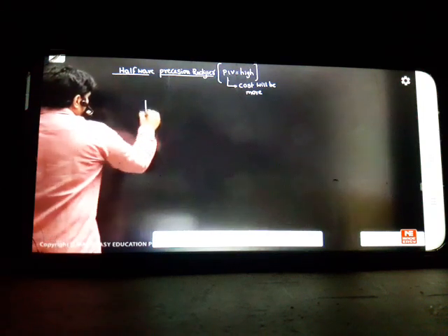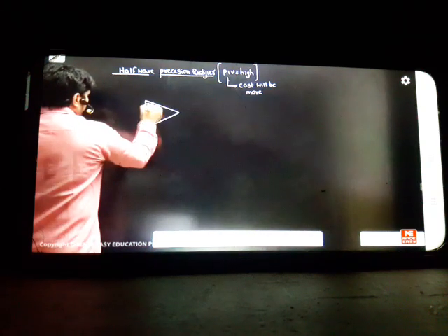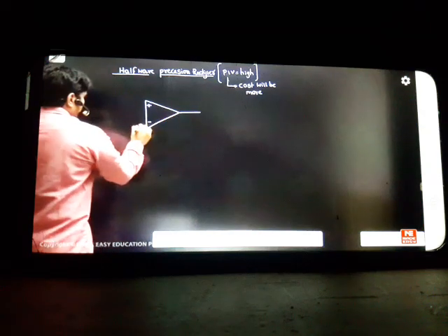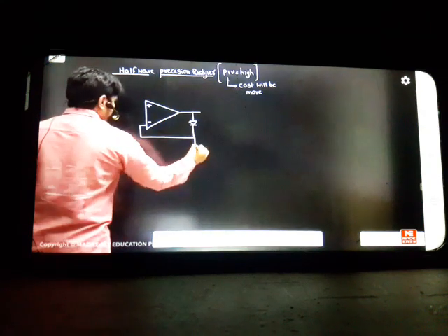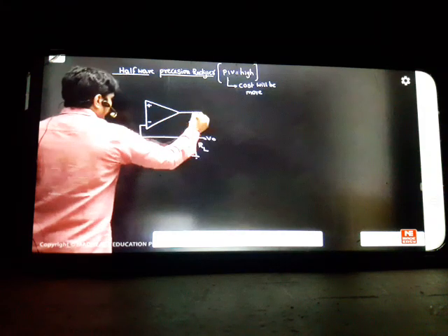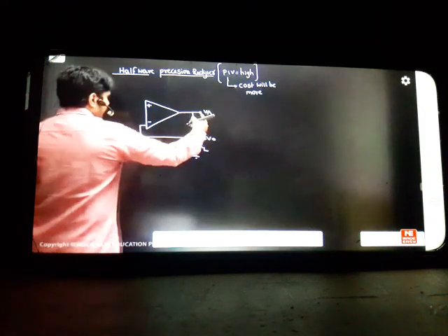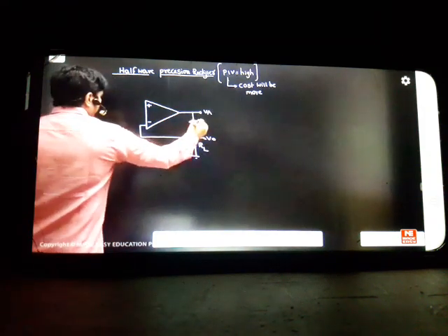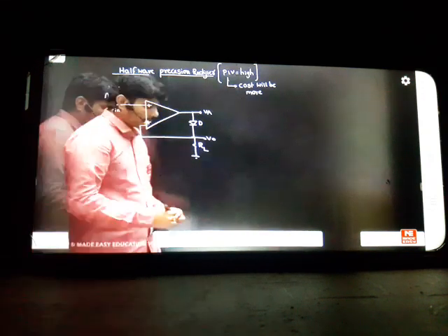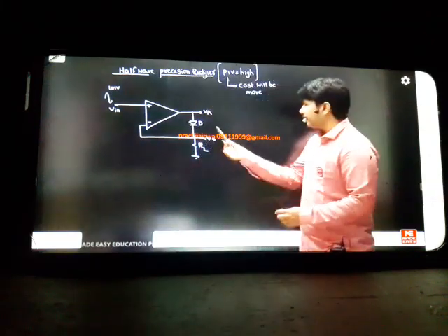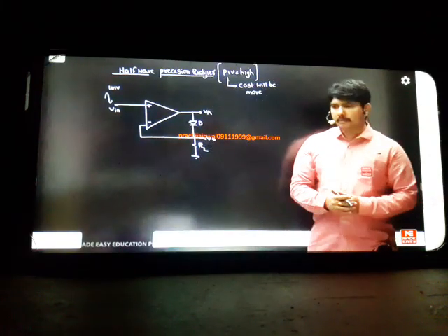In this circuit, how PIV will be high, we'll discuss. First see the circuit. The person started to design a circuit like this. This is the plus, minus side. I connected a diode here as feedback with a load called RL. You're taking the output across the load. This is the op-amp output, VA. Take two different outputs: this is the op-amp output, this is your load output. In between there is a diode. Now I have given here a signal called VIN. The VIN signal is 1 millivolt, suppose. Now you have to rectify the small signal. Examiners will give questions like this. They'll give op-amps, they'll give diodes, sometimes they'll give BJTs, as you have seen in the workbook. Whatever they are keeping, what is the principle behind this?